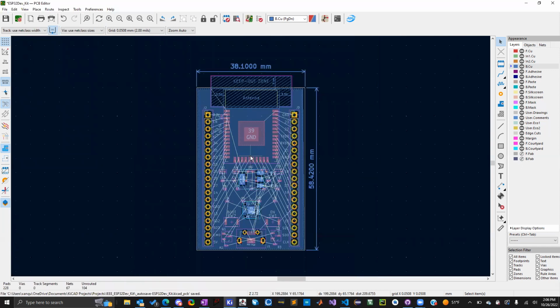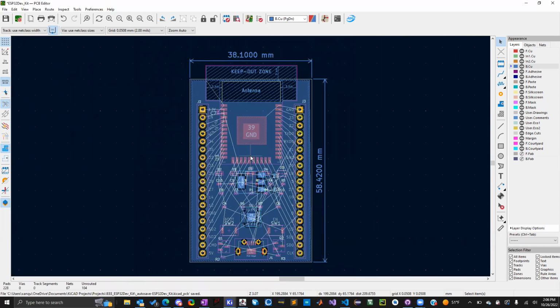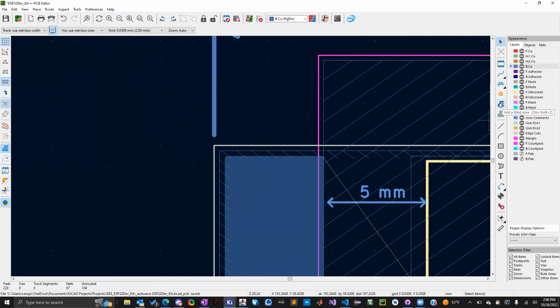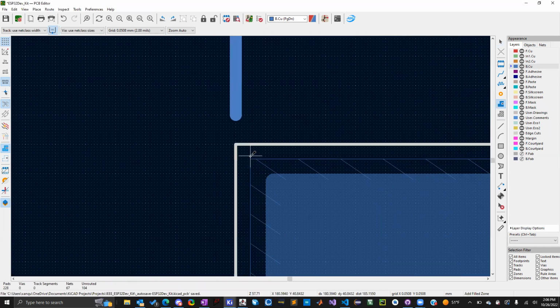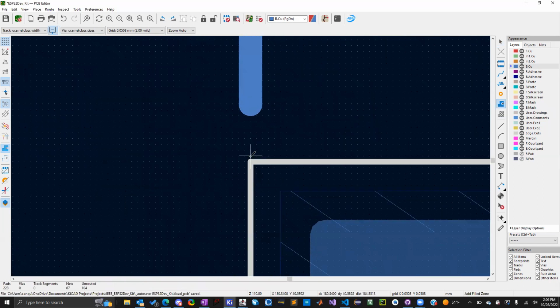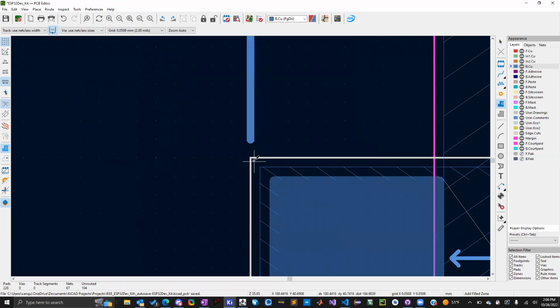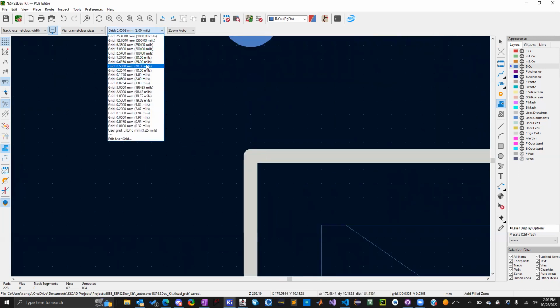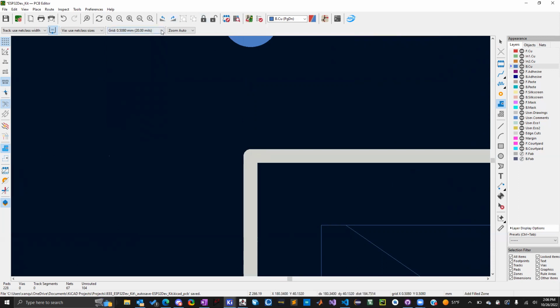All right. So do you guys have the whole layout for your boards and everything? Sure. To do the zone, you're gonna go to the right here, add a filled zone. You're gonna click on that, and then you can just pick, you can even do the corner of the actual board. It doesn't really matter. There's gonna be a certain clearance for the edge of the board and the copper, so it will automatically control like where the copper is placed. But you're gonna click on like the top left corner of your board. Might want to change your grid size so that you line up with your